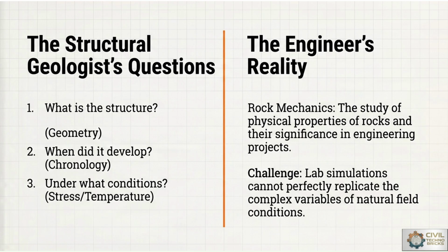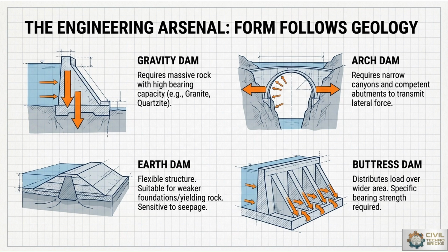So there are many challenges, like lab simulations cannot perfectly replicate the complex variables of natural field conditions. The laboratory tests provide us useful data, but actual field conditions are more complex due to the groundwater, weathering, and in situ stresses. So proper geological interpretation is most important and essential for selecting a safe dam site, dam alignment, site selection, and preventing foundation failures. With reference to the type of dam, the engineering